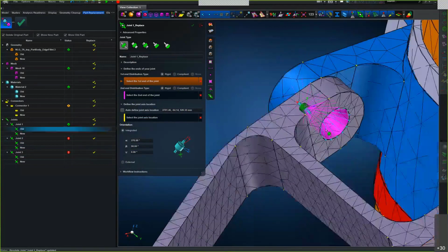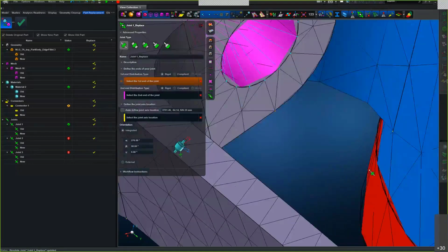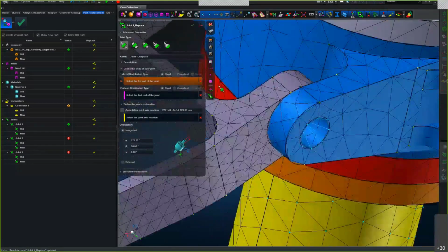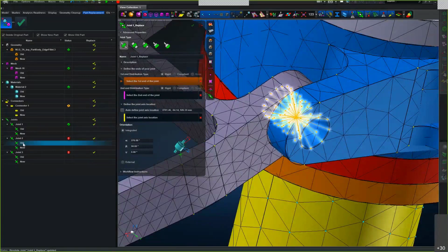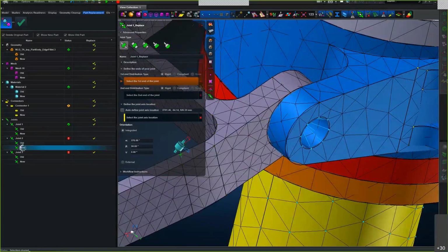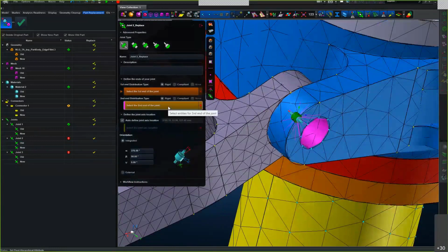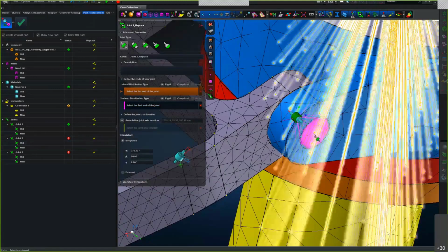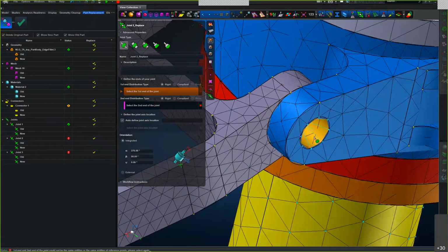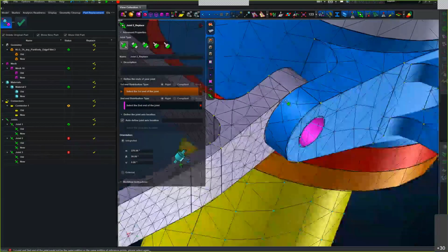If you think about most things like joints and loads and boundary conditions, they mostly fail to map because we're unable to find the application region on the new part from the old part. So this correction tool is simply an application region finder. You just fire up the tool, you find the first end of the joint, it looks good. I'm not entirely sure why it's not. It's like it's found the same end twice. Let me go to the other side.